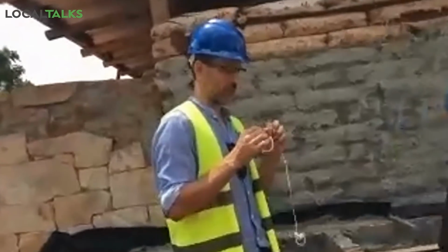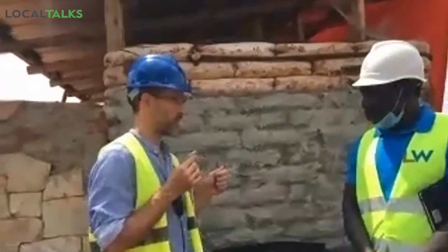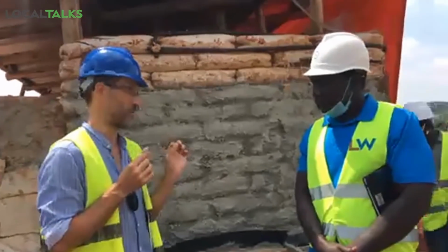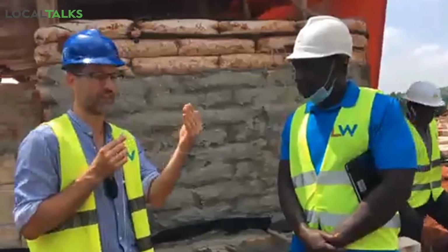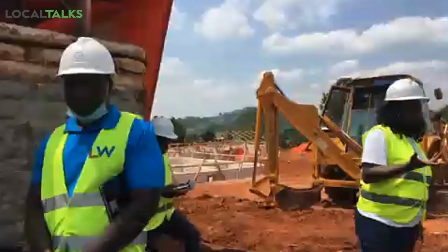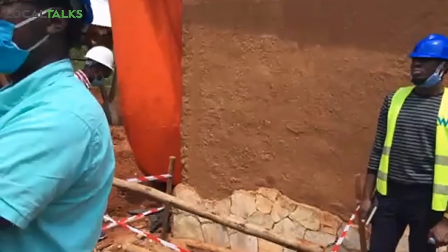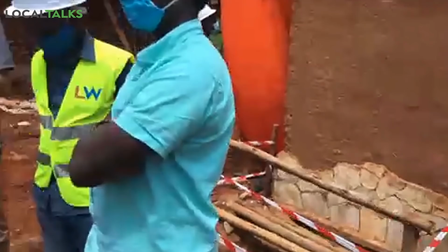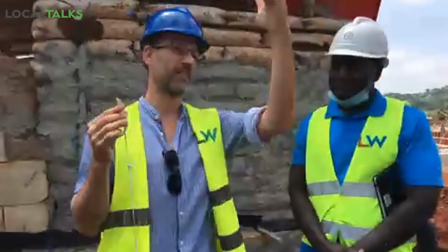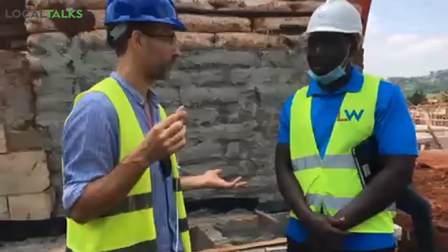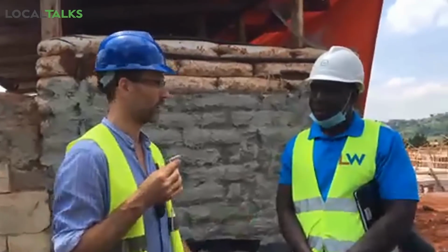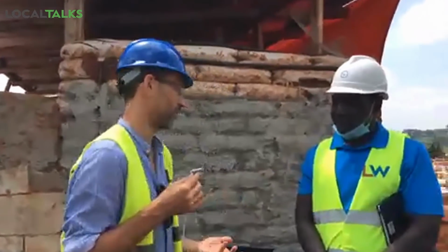Well, as I mentioned before, we are not actually leaving them completely open. We are going to put in an earth mortar basically for visual reasons. That earth mortar is going to be slightly recessed, and it will combine with the earth plaster from above. That's the whole idea, so that we tie them together on an architectural level. And that means there are no big cavities. A bit of algae depends on the way. For instance, this side will probably be exposed a bit to the rain, so a little bit of weathering of stonework is perfectly acceptable. That's the whole beauty of stone. It can deal with it, so we are not afraid of that. It can also be cleaned off any time if people want to.